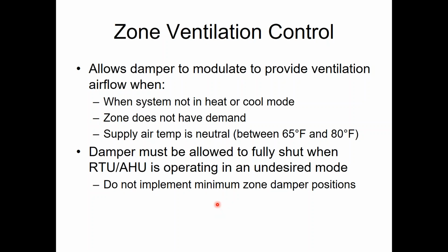From a ventilation standpoint, it's going to be very difficult for you to comply with ventilation code with a VVT style system. VAV, it's difficult. VVT, it's almost impossible. The reason being is if you've mixed zones that want both heating and cooling, you absolutely, positively, no matter what, have to let the dampers shut all the way down to 0% open in the occupied mode, which means you can't comply with ventilation code.